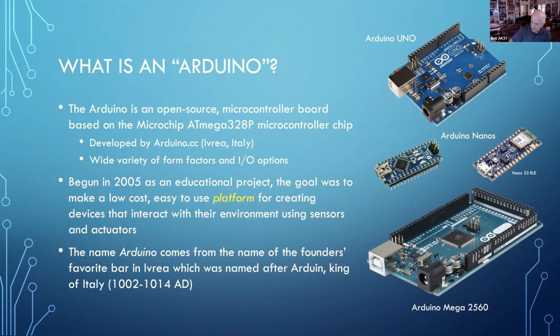board. And you'll see, for example, if you look at this little module here, this is the Arduino Nano, and you see in here is the microcontroller integrated circuit, and all the rest of it is peripheral circuitry that allows it to talk to the outside world. It has a USB interface, it has a serial programming interface, it has a number of digital ports, a number of analog ports, it has a crystal oscillator, which is on the other side, it has a reset button, et cetera, et cetera. It's got a bunch of LEDs. Lots of things are built onto that individual circuit board